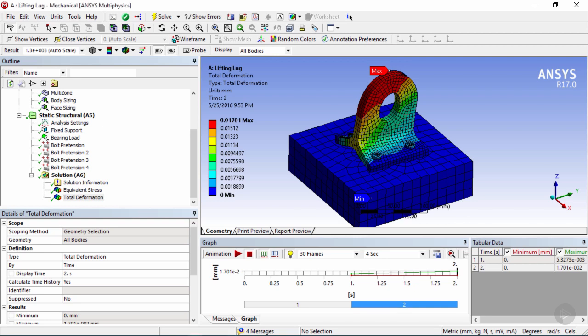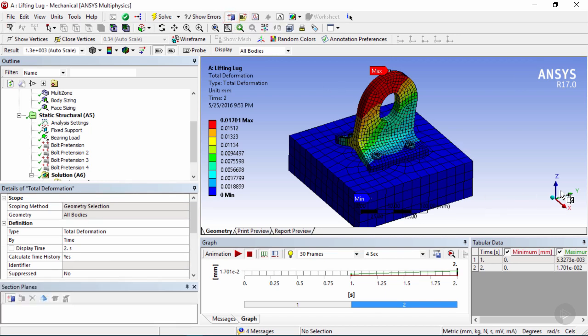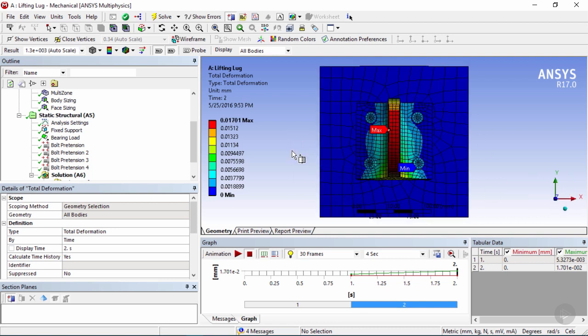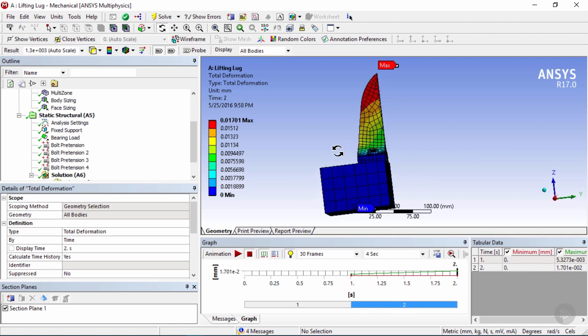Now let's say you want to create a section plane of your model. You can go ahead and click on this button over here to create a new section plane. So click on that right now. Now let's say you want to have a nice section plane. We can click on this Z normal right here to look normal to it, and then we can drag a line, clicking the left side all across to the right and then releasing the click, and there you have your section.